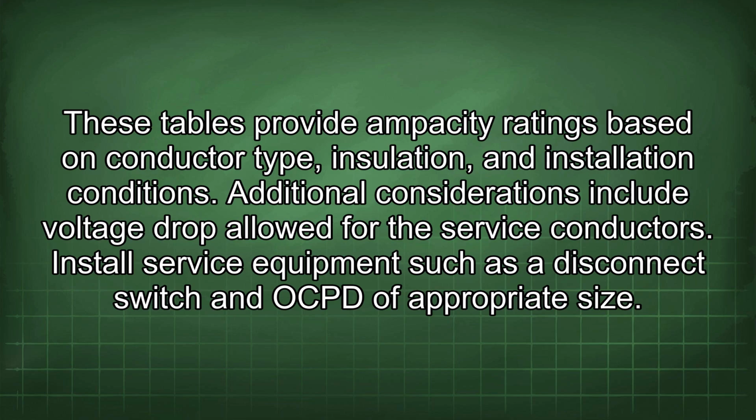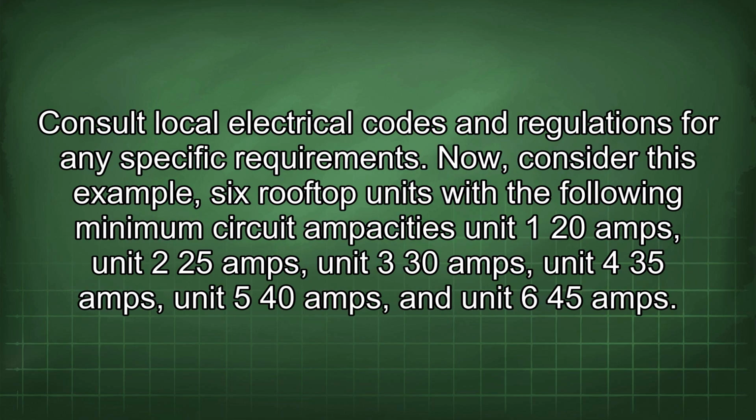Additional considerations include voltage drop allowed for the service conductors. Install service equipment such as a disconnect switch and OCPD of appropriate size. Consult local electrical codes and regulations for any specific requirements.